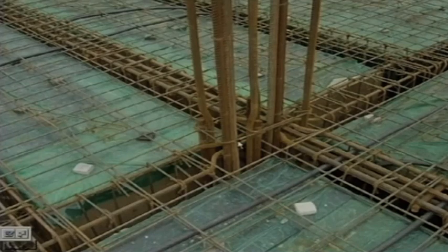What you have to do when you are talking about reinforced concrete is consider what gaps should be provided here, because whenever you are giving the reinforcement detailing, you also have to take care whether you have sufficient gap for your coarse aggregates, because it depends on the coarse aggregates. Otherwise, at the time of casting, if proper vibration is not done, there may be a void in the concrete, which will weaken the concrete. Though you have designed for M20 grade of concrete, you will not be able to achieve that because of these voids.